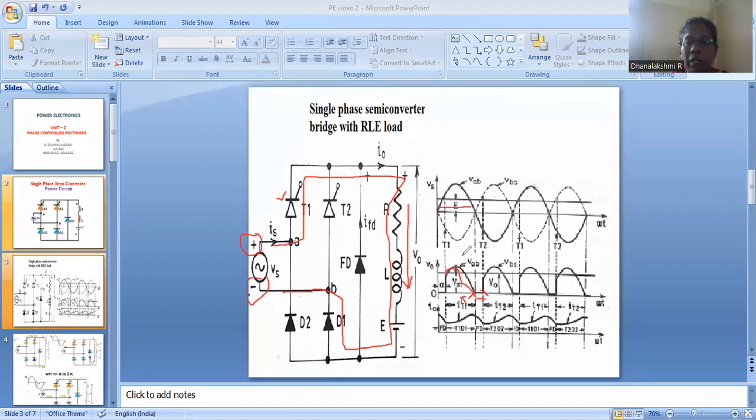During this freewheeling period, the inductor releases all its energy through the freewheeling diode. The freewheeling diode creates a freewheeling path for the inductor to release its energy. When the freewheeling diode is conducting, it is shorted, and as we know, the voltage across a shorted path is zero. If the voltage across the freewheeling diode is zero, then the load voltage should also be zero.